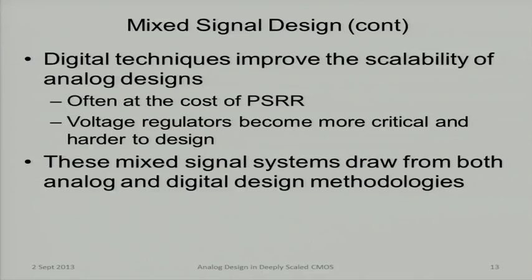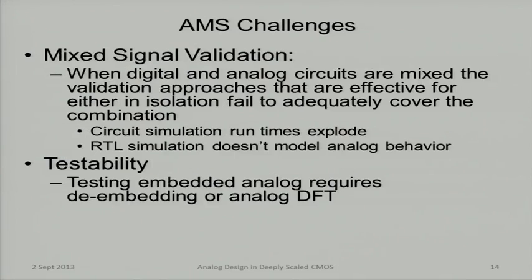Sometimes applying these techniques, if I do simple digital oscillators from my PLL, I actually hurt my power supply rejection ratio, which means voltage regulators become more critical. Those voltage regulators got harder to design. But perhaps more subtle, I have to draw from both the analog and the digital design methodologies in what I'm doing, and I have to put them together in the same subcircuit. And that's not a free lunch.